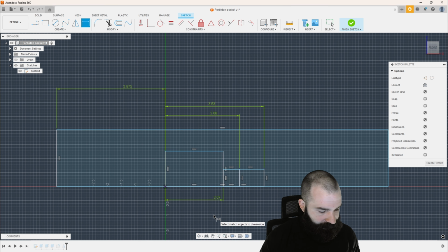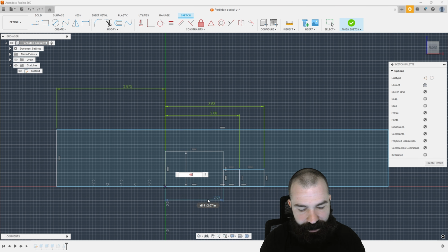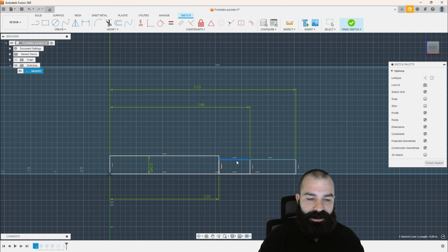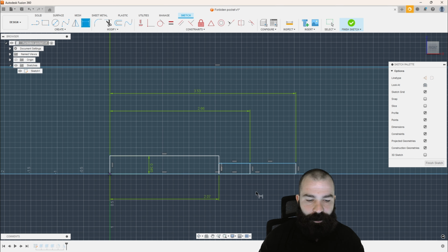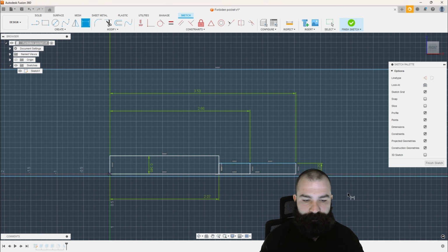Lastly, I'm going to plug in some widths now. So let's find my width dimension. We have a width of 0.69 from here to here, and that is going to be 0.69 divided by 2. Again, I'm going to grab some of this and pull it down to get it very close to where I want it. My next dimension is going to be a 0.50, so again, we're going to take this one here, 0.5 divided by 2.